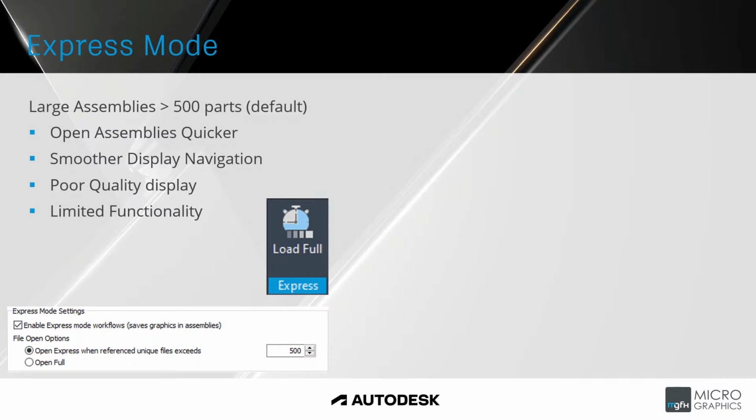So it opens quicker. It allows you to open large assemblies quickly, let's say, to show a manager something if he has a question. You don't have to wait for the full assembly to load. The navigation, so orbiting and navigating your model, is smoother due to that reduced graphics quality. But as I said, we get that poorer quality display, and you're also reduced in your functionality within the assembly.